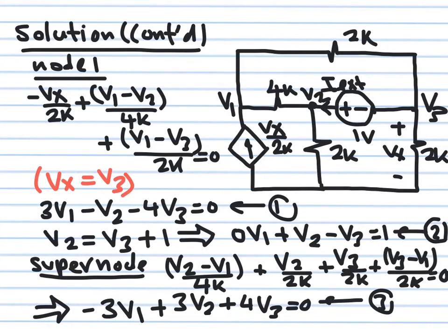Okay, so this is how the circuit has been drawn after I got rid of the independent sources and after I put a 1 volt external source. Remember, my target is to find the ratio between this 1 volt and I external. This is a circuit like any of the circuits we dealt with in this course. We have how many loops? A loop, a second, a third. We have how many nodes? A node, a second, a third. I prefer to use nodal analysis here. So let's apply KCL here.